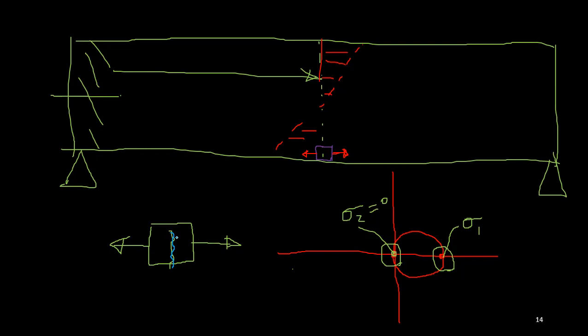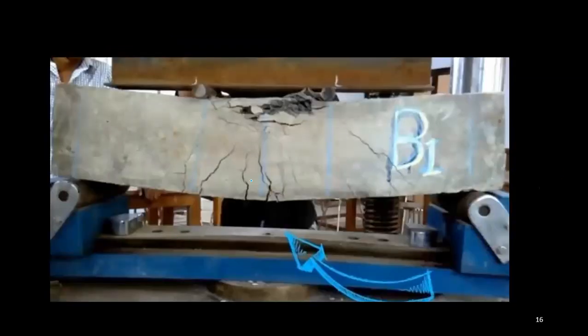So this is also actually visible. Can you see these are the flexural cracks? Those are vertical, normally going bottom to top. Why? At the bottom you have maximum tensile stresses, where your crack initiates, right? And near the support you can see both flexural and shear cracks, flexural shear cracks, right?